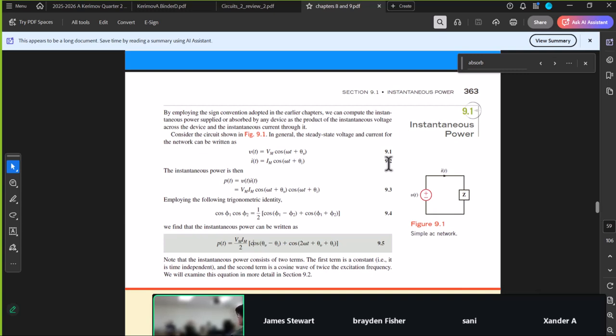Absolutely. And so if you had a circuit, for example, that had 2 power sources, and you compute it and you find out that they're both absorbing, you know you did something wrong, because you can't have a circuit with 2 power sources that are both absorbing. Now, one absorbing and one supplying is fine. It's possible they can both be supplying at the same time.